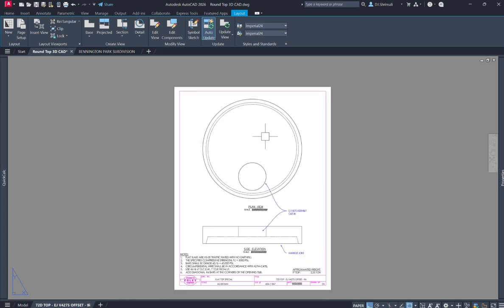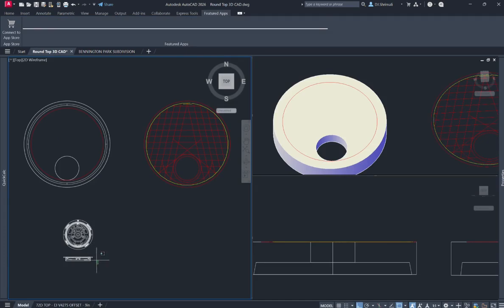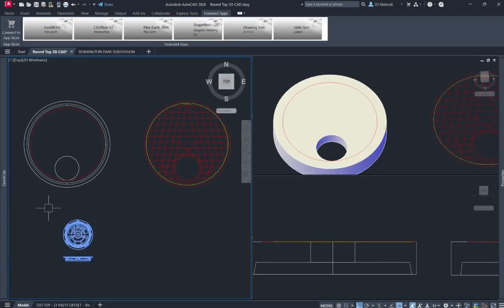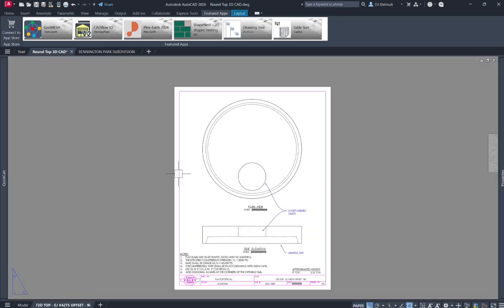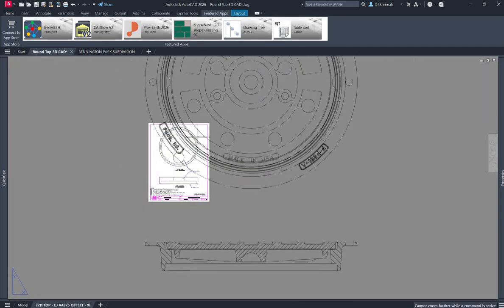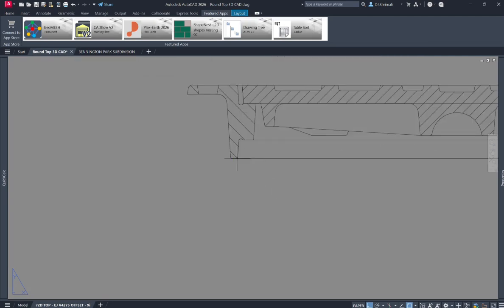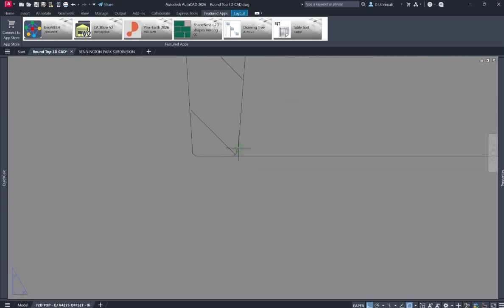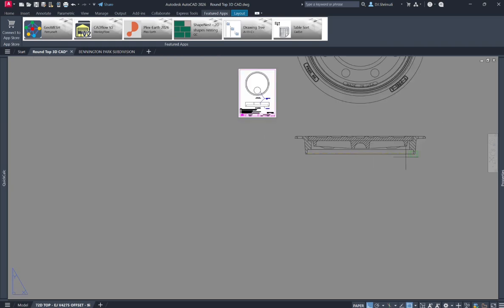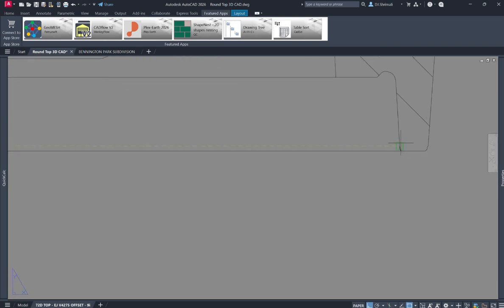So next step, we're going to put the hatch or casting. We're going to Control Shift C, copy, and Control V, not Control Shift V. Control Shift V creates the block. So we just paste with Control V, which will just paste the object. Now we're going to scale it. That's the inside dimension, our opening at the bottom of the concrete.